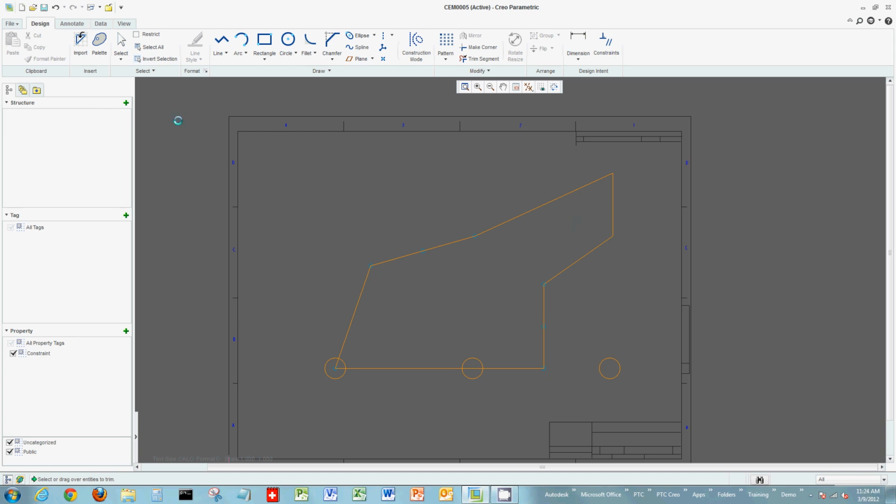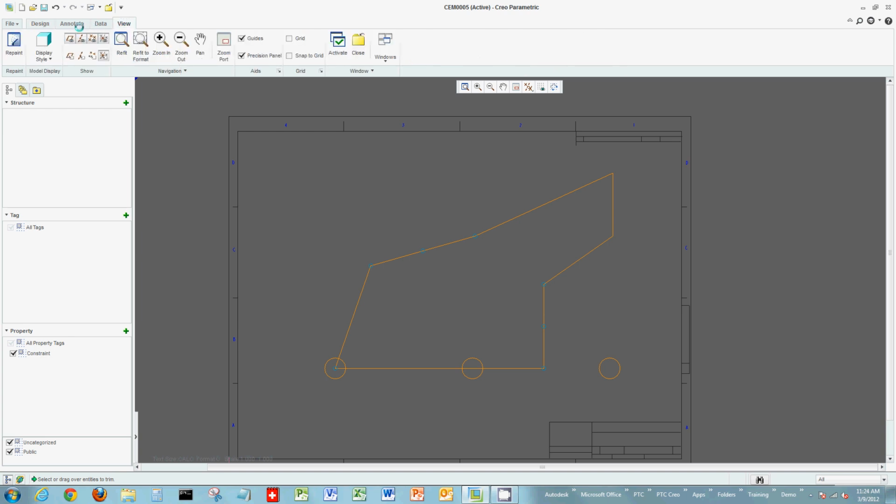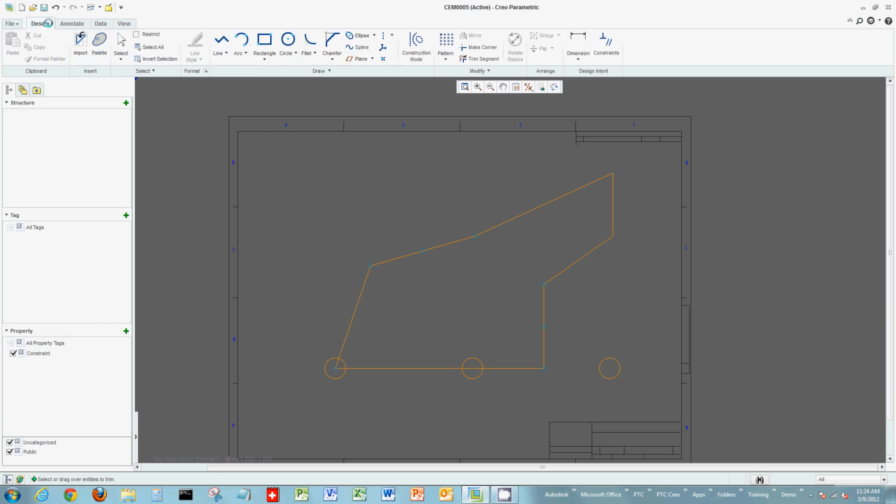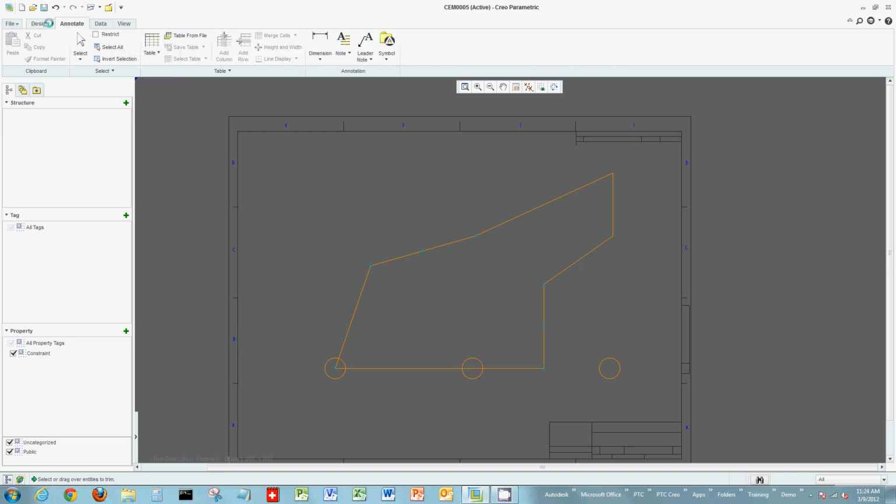Also, same as you have in Creo Parametric, you have your tools to analyze your sketch once it's completed, to see if it's a closed loop, if it's actually part of the design which you're looking at, or I can display open ends. So a variety of different tools you can use within the actual annotation of the elements.